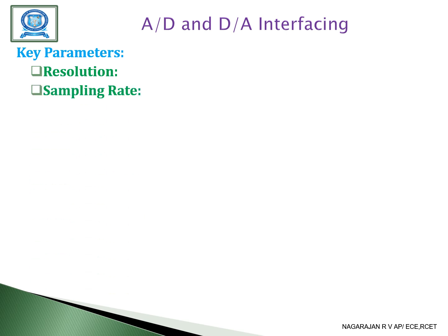Next one is sampling rate. This is the frequency at which the analog signal is sampled. Higher sampling rates capture more detail from the analog signal but require more processing power and storage. And next one is accuracy and linearity. It measures how closely the digital output matches the actual analog input. Non-linearity and errors like offset, gain and noise can affect accuracy.